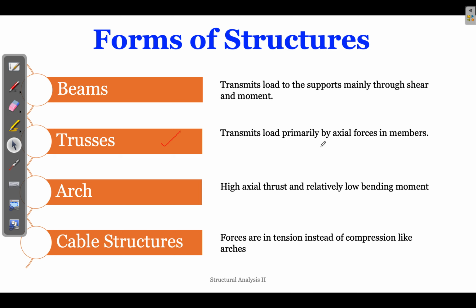Suppose there is a truss, let us consider this small truss, and some load is acting here. So axial forces will be there in the members, and the top chord will be under axial compression and the bottom chord may be under tension.